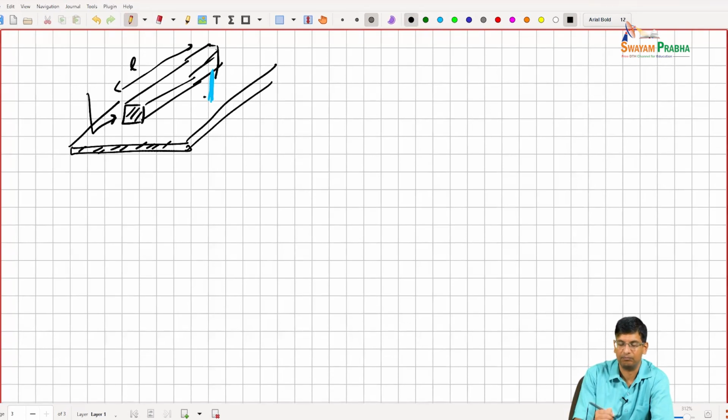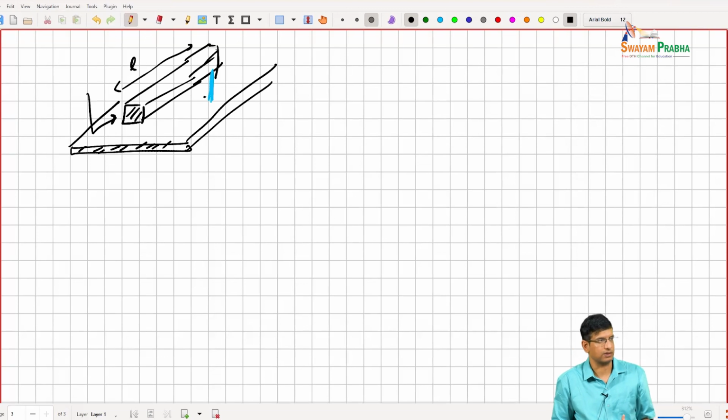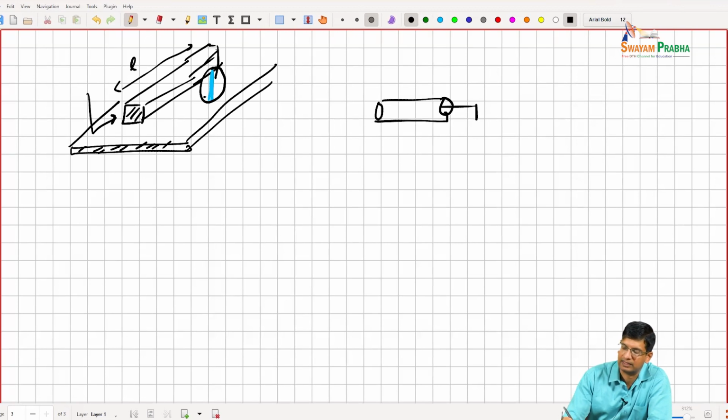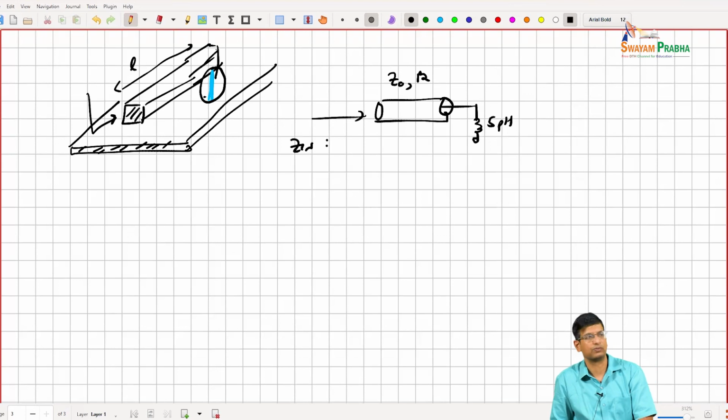Then when we look at the impedance here, it looks like an inductance. To be very precise at millimeter wave, we might also model this via, which is typically an inductance. So we might build a slightly more complex model where we terminate this in, let's say, 5 picohenry, the model of our via short. Then we decide on Z0 and beta, and we want to get a Zin that looks close to an inductance. So we can build circuits like that.